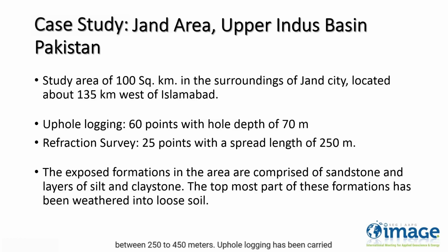Uphole logging has been carried out at 60 points. The geophone offset is 2 meters and the hole depth is 70 meters, with 20 shots at different depth intervals. Refraction survey has also been carried out at 25 points, each having a spread length of 250 meters.